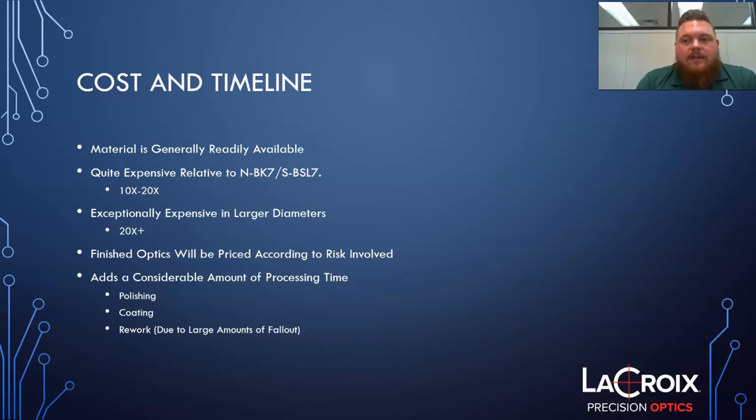With regard to coating, as we previously discussed, there is an additional amount of time necessary at both the beginning and end of the coating process because the temperature in the coating chamber has to be raised and lowered very slowly in order to keep from shocking the parts thermally so that they do not fracture.